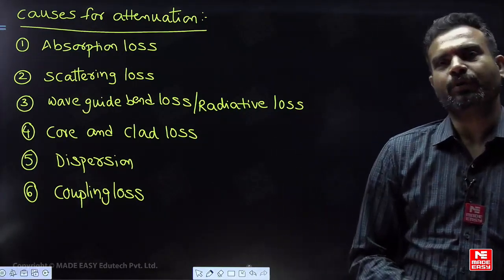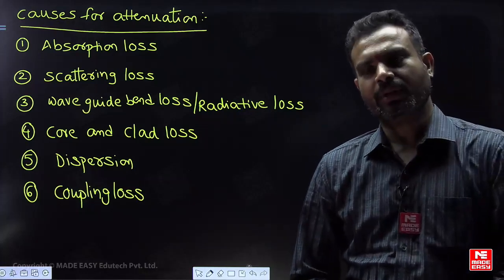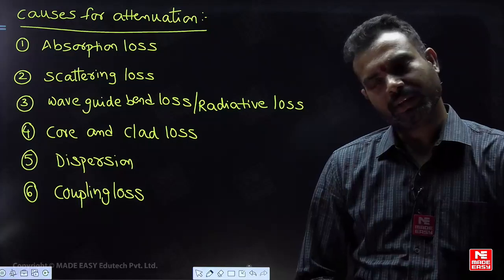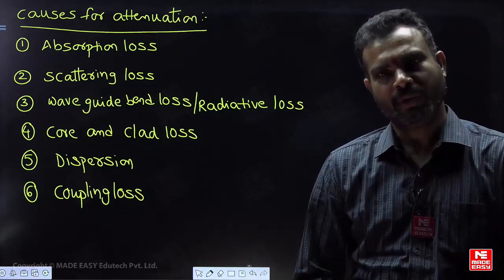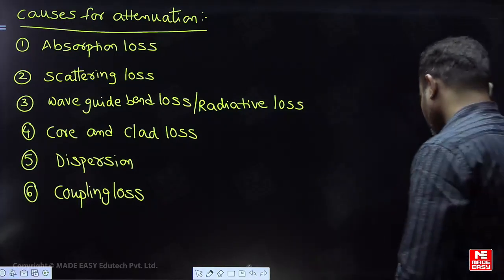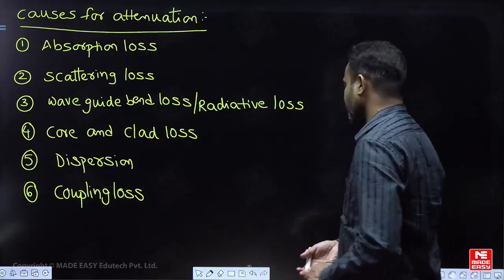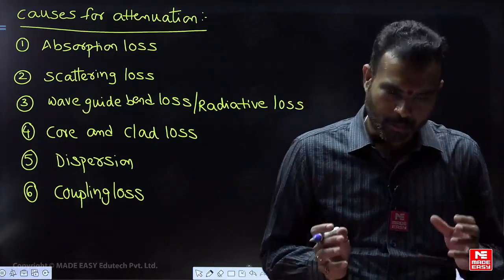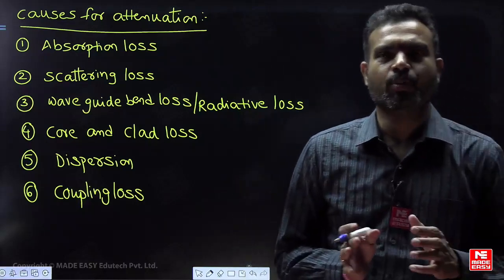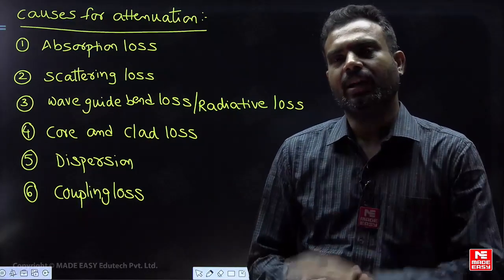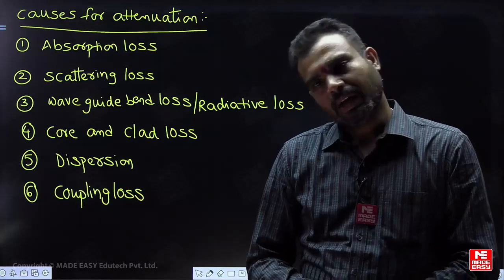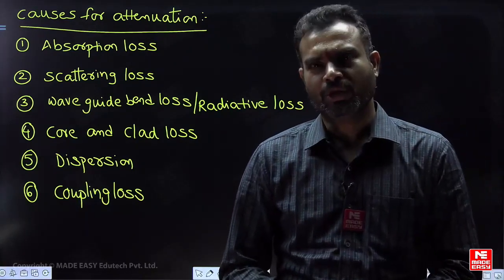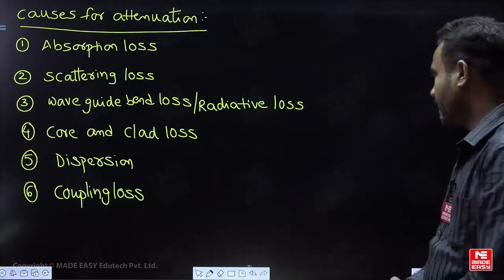The amount of loss offered by copper cable is 20 dB per kilometer. The amount of loss offered by optical fiber cable, OFC, is 0.2 dB per kilometer. I hope you already wrote this point in yesterday's class. In yesterday's class we stopped our explanation at modern telecommunication using 193.1 terahertz at 1552 nanometers. I hope everybody has recalled the entire concept and revised it.